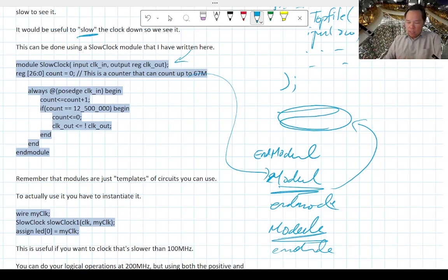Okay, so that does happen. Just make sure your top file is the first set of code that gets synthesized, because it's kind of like the mother module, and it calls other little baby modules around. Okay. All right. So let's see how this works.